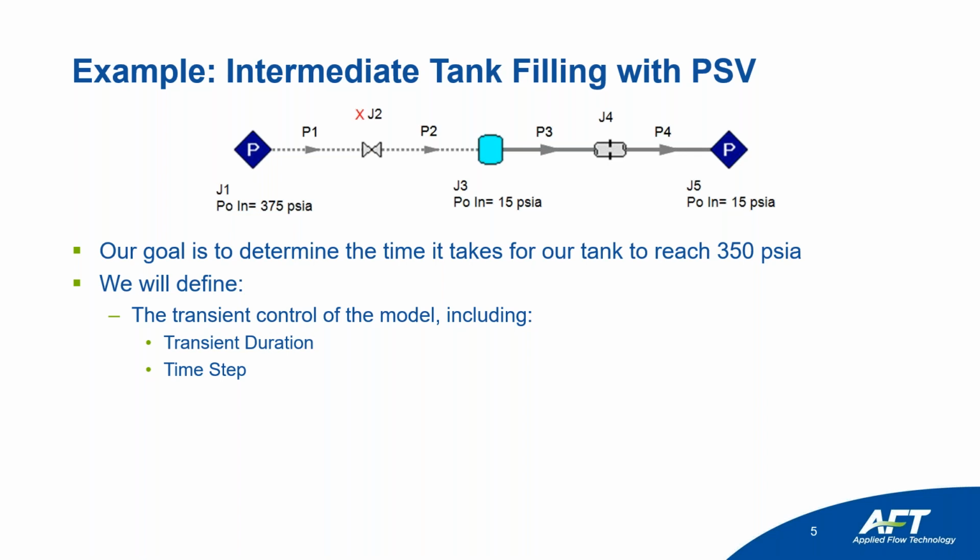Then a superfine time step might create issues, especially when you have hundreds of simulations that you're trying to run across your transient. So something that you'll consider, especially if you start experimenting with the XTS module, if you start doing this analysis yourself, you can make this finer or coarser. And as a result, that'll impact both your runtime and ultimately the accuracy of your results. So as an engineer, it's your responsibility to take a look at that. What is reasonable? How do you balance those two variables?